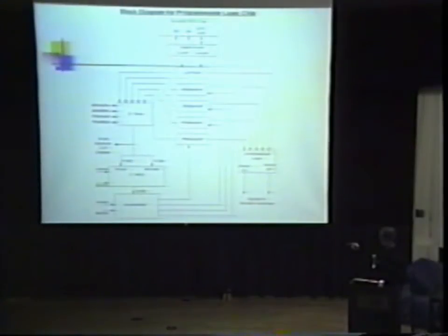Then those 8 bits are restored back into one of the 4 alarm times. The 5 registers are then sent to a combinational logic block, which uses combinational logic to match the current time to the alarm times and sends out 2 signals to the elevator controller.